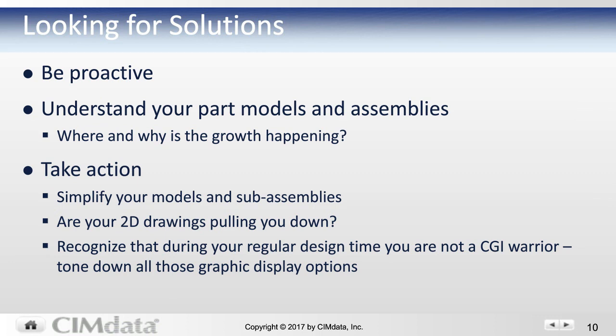There are 3 different actions that we often recommend at SimData that a designer take. First, simplify your models and subassemblies. Well, what does that mean? If you're adding fine detail to the geometric model shape before you've even settled on some of the major aspects of the design, then you're carrying a lot of baggage around as you do those major aspects.